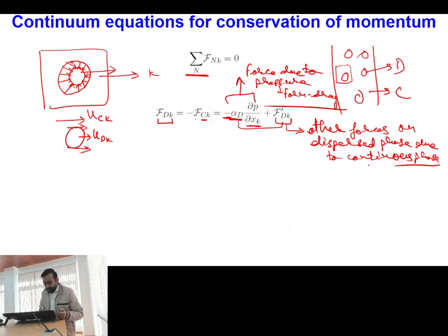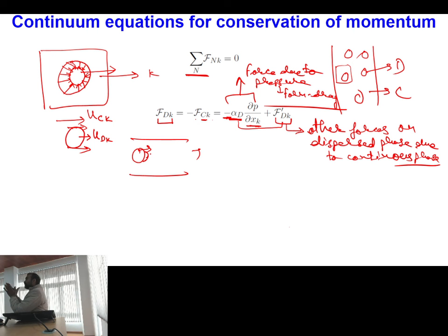The meaning of added mass force is, say your flow is happening in the rightward direction and a particle is moving in the rightward direction. Immediately in the vicinity of the particle there will be some portion of the fluid which is sticking to the particle, which will lead to an increase in the total mass being pulled in the rightward direction.